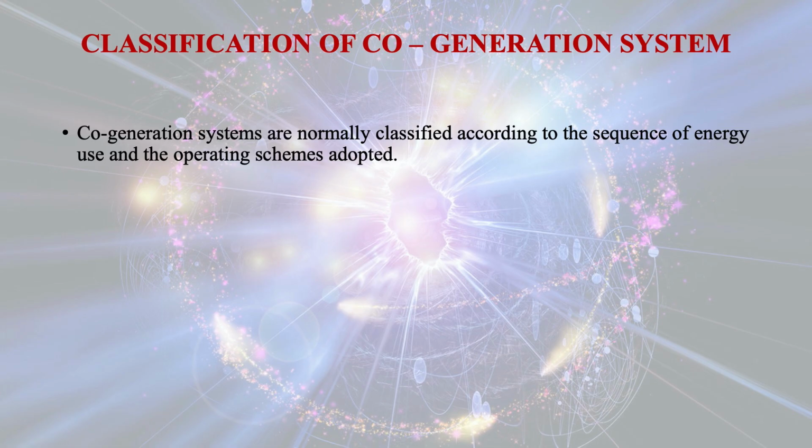Now this is the TS diagram of regenerative cycle with 2-feed water heater. You see that 1 kg of steam is entering at the inlet of the turbine. At stage 2, m1 kg is leaving the turbine and entering into the heater 1.